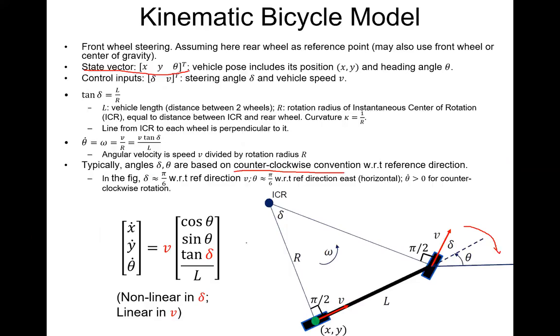So somewhere you have a global point of 0, and somewhere you have a global direction of 0, for example, east. It doesn't matter how you define the global coordinate. The point is that they're global. They're in reference to a global reference frame. And then the steering angle delta is in reference to the vehicle's heading direction. So delta is in a local frame. Yeah, and the error is if you're to the left of the road or to the right of the road.